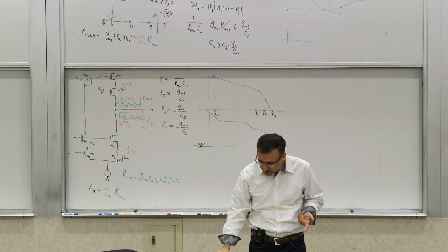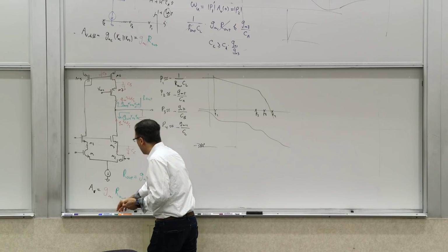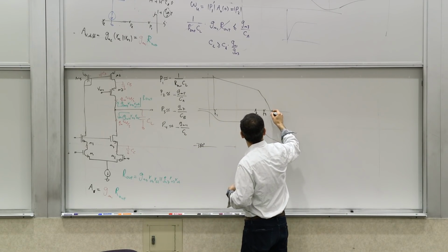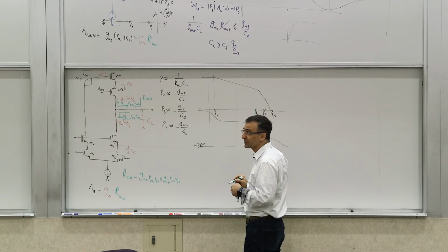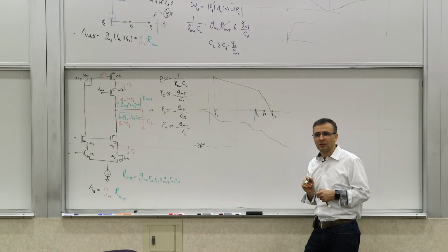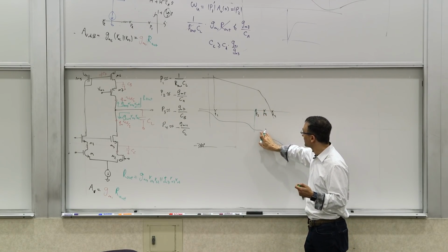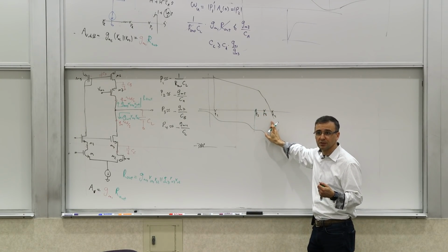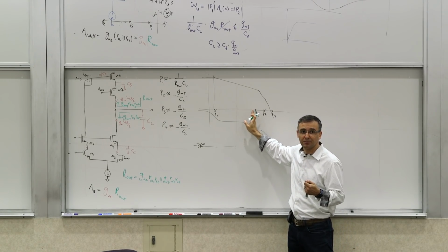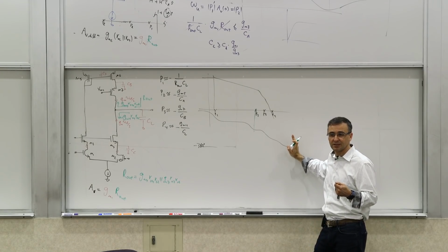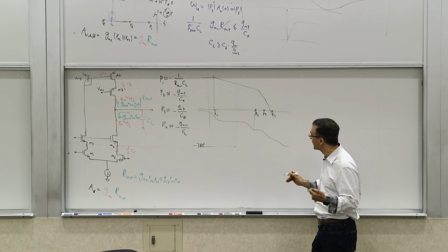So how do we compensate this? Again, the trick is to push this out so much that the unity gain frequency happens around here or before, where you have some phase. Now, if these poles are close to each other, the phase contribution of these subsequent ones is important. So you may not even be able to shoot for here. You may have to shoot for somewhere lower than that, because these are 3 poles, each introducing a fair amount of phase that can extend back.